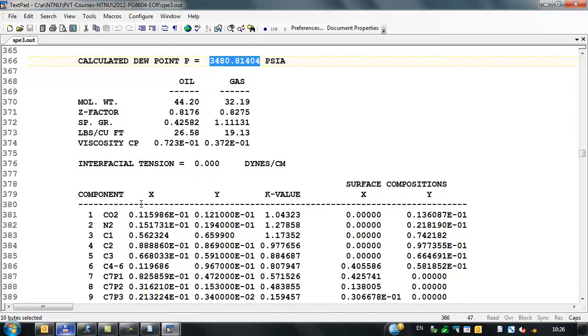Okay. So we've got enough stuff coming from the simulator to make sure that when we bring this into the EOS simulator phase comp, we should get the same saturation pressure, the same K values, the same densities of gas and oil, same viscosities at the saturation pressure. And if we don't, then we've done something wrong in taking the EOS and composition from one model to another. Okay?